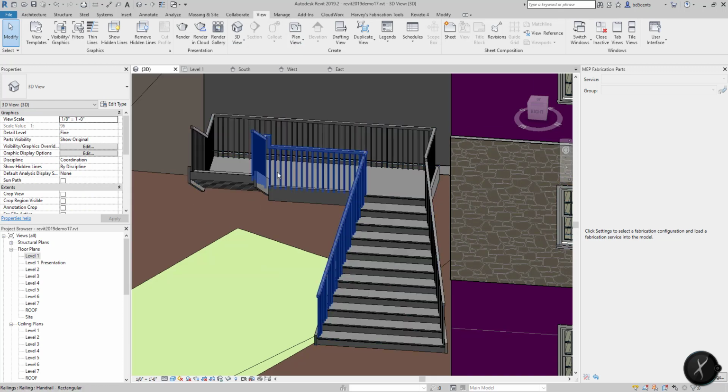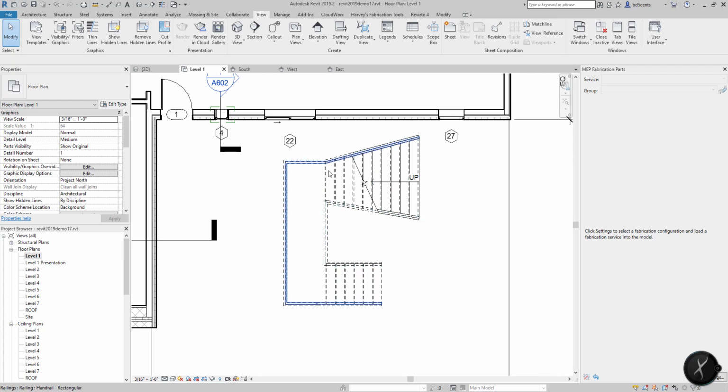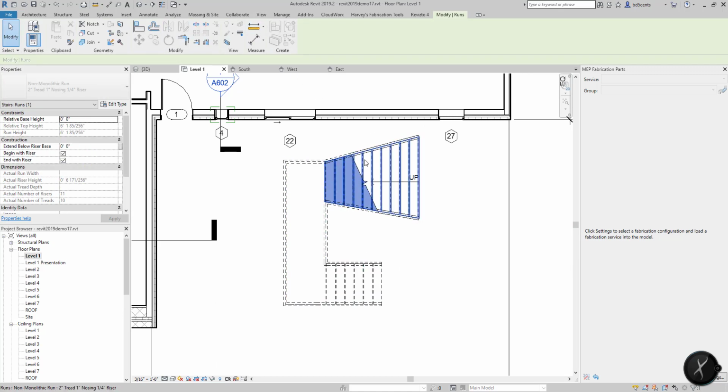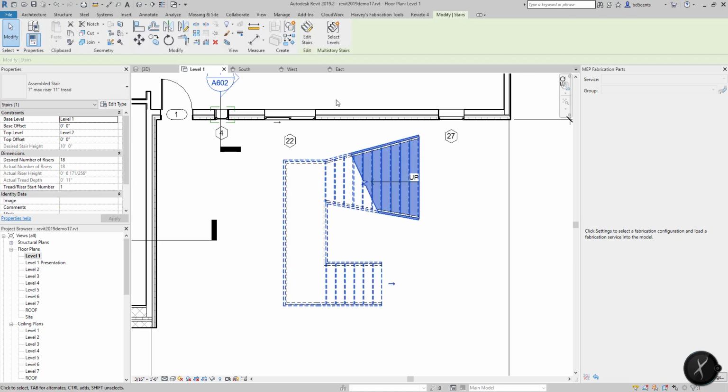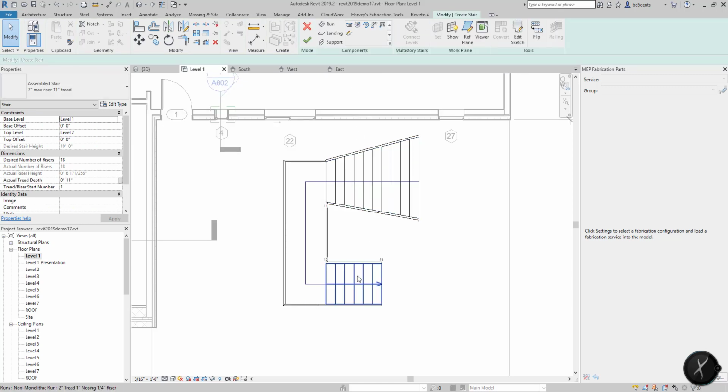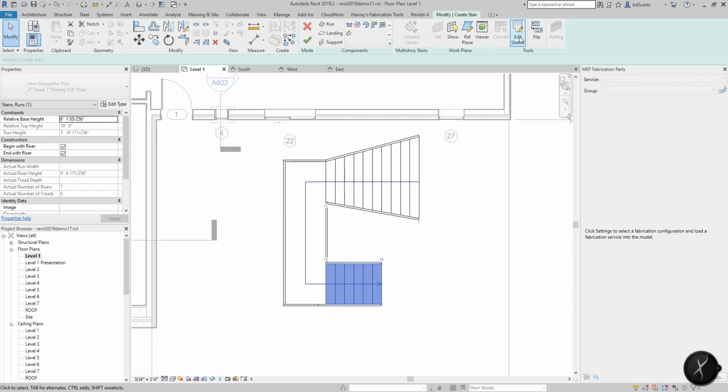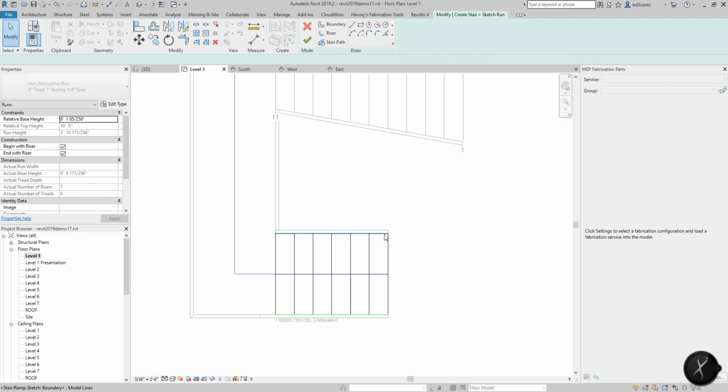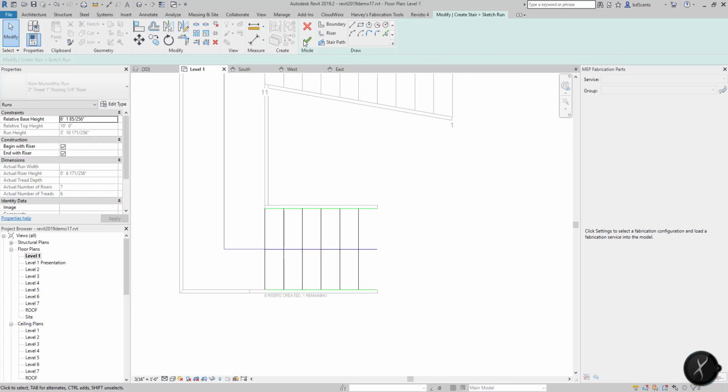So they're very dynamic of what you can do with stairs. So we've gone into those different areas. We've edited our stairs footprint. We now want to delete the 2 high horizontal green lines on the upper stair. So if I go up to level 1, edit this sketch of the stair, or edit the stairs, come into here and edit this sketch, I can delete these 2 boundary lines, or I can delete this boundary line.